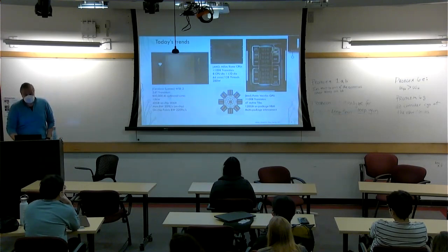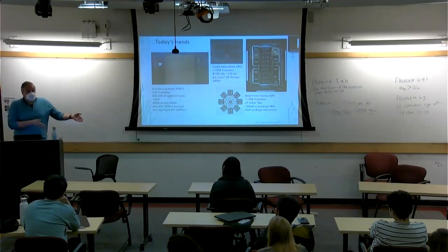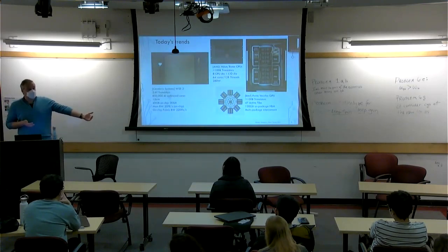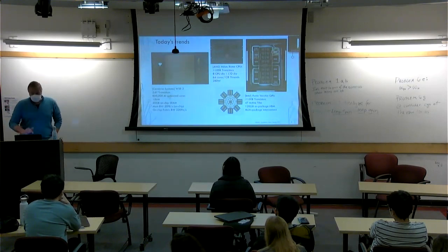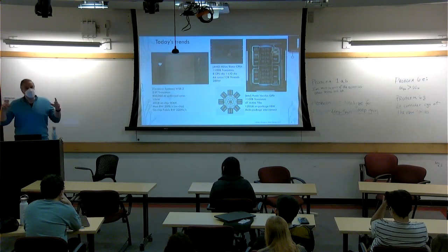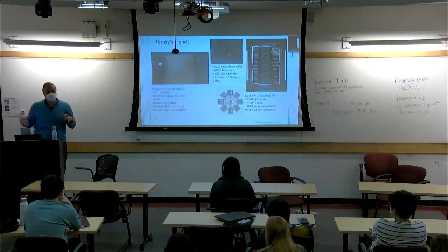And then you have this middle chip, which is the IO hub. This one hosts all the SerDes, all the memory interfaces, DDR, etc. That one stays at 16 nanometer for several generations now, because those things are hard to design, port and validate, and they don't actually benefit that much from going to the next node, because these are analog mixed signal circuits and things like that. They don't really scale that well in more advanced digital nodes. But what you do is add some lightweight links between all of these cores and the IO, and that represents a different view on the network on chip, right? It's really network on package, right?